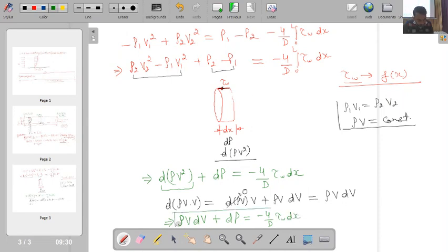Now the beauty of this equation is that this momentum equation is applicable for any type of fluid that involves friction, because till now we have not made any assumption of a special type of fluid, and shear stress is also a generalized term. If I substitute this for a Newtonian fluid, then this equation will be applicable only for a Newtonian fluid. Now with this equation, let's deduce it for the case of a calorically perfect gas.